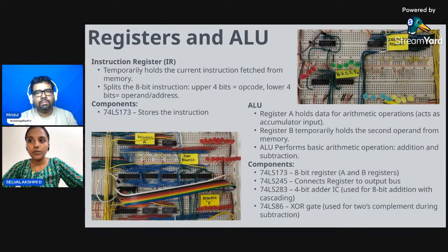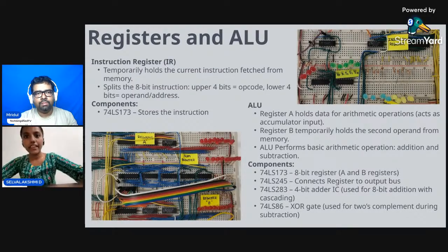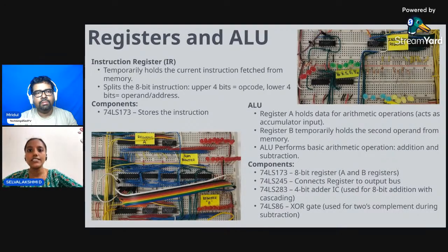Yes, a register is nothing but a place to store things we require. To store our data, we require a register. In registers, we are storing the data with which we are going to perform logical operations. We have the instruction register, register A and register B. We have three registers. The instruction register stores the instruction and it is a 4-bit register. We can have only 4-bit data in our instruction register, and register A acts as an accumulator.